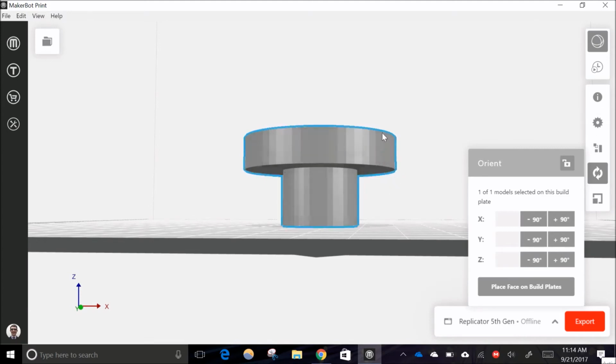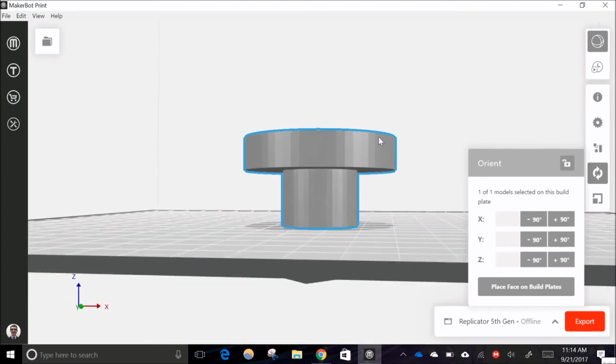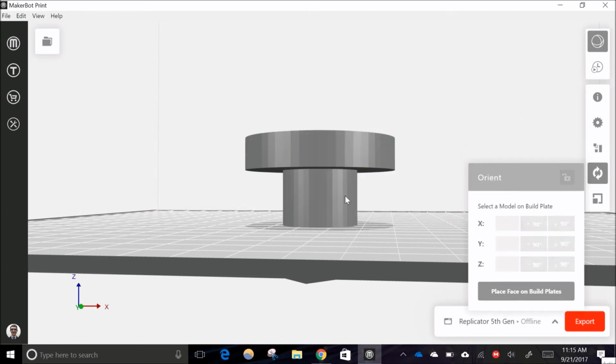The thing is, when it's printing, the 3D printer can't print this ledge here without something underneath. It can't print in mid-air. So it creates this thing called support material, which in the end you're going to have to scrape out yourself and break apart. It's somewhat annoying, so you don't really want to deal with it, and it also makes the surface not look super clean and smooth. But sometimes it's unavoidable.